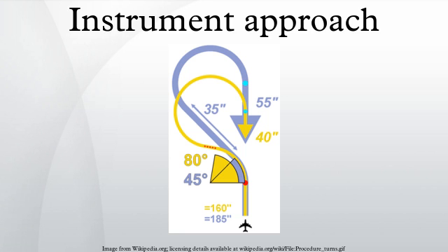According to ICAO Doc 4444, ATC continues to provide separation between the aircraft making a visual approach and other arriving and departing aircraft. The pilot may become responsible for the separation with a preceding aircraft in case he/she has the preceding aircraft in sight and is instructed so by ATC. In the United States, it is required that an aircraft have the airport, the runway, or the preceding aircraft in sight. It is not enough to have the terrain in sight.